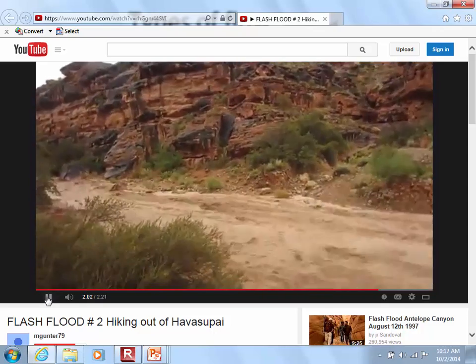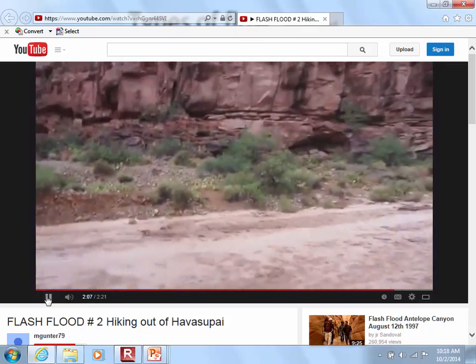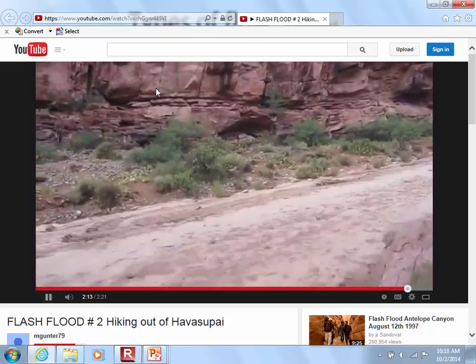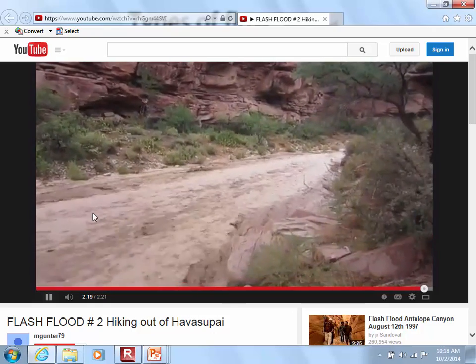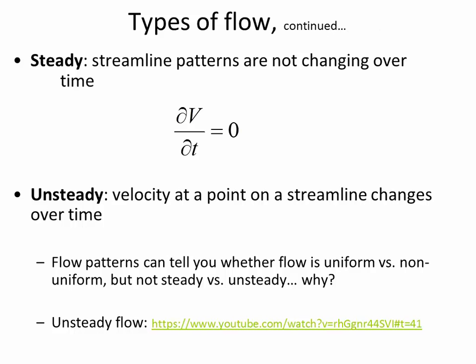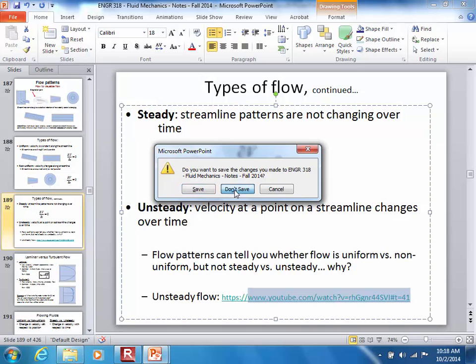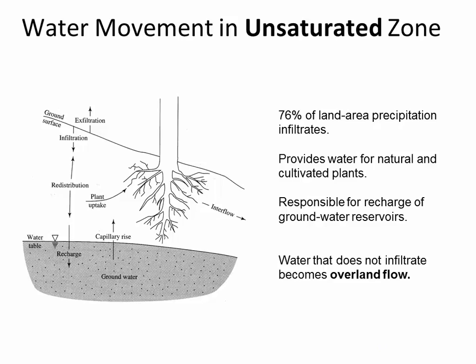That is so deep. Sweep you downstream. So this is why we are studying infiltration, because in rugged canyons like this the rock is not infiltrated. Even though the soil is dry, this creek bed was dry before the event started, the water is arriving so fast that it's immediately exceeding the infiltration capacity. The reason why there's runoff is because the precipitation rate is so much larger than the infiltration rate. Good video, right?